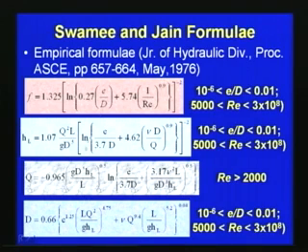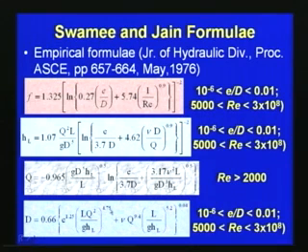And then they also derived an expression to design a pipe. While designing the pipe for a given discharge, it depends upon various parameters. Based upon these equations, Swamee and Jain derived an expression directly for the diameter of the pipe: D is equal to 0.66 times e to the power 1.25 L q squared by g h_L to the power 4.75 plus nu q to the power 9.4 L by g h_L to the power 5.2, all to the power 0.04. Here h_L represents the head loss.